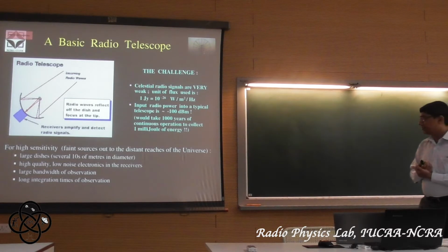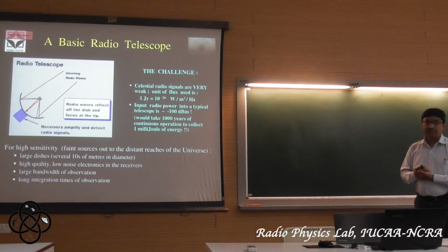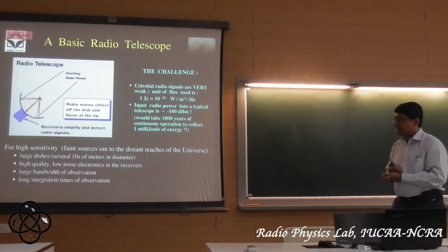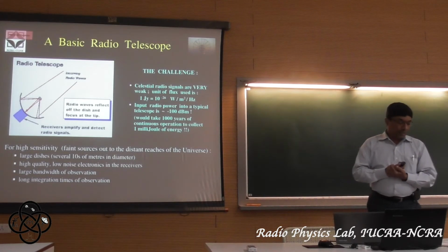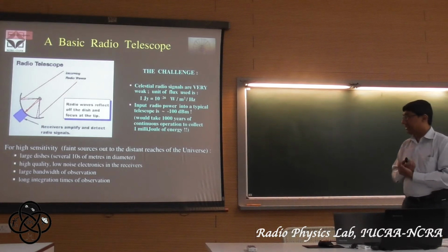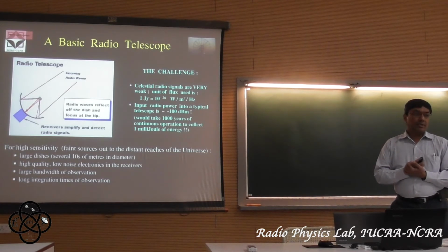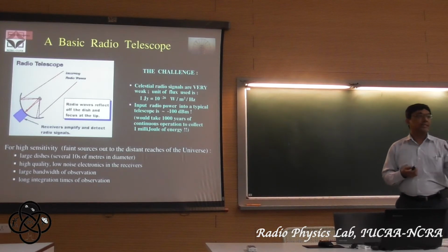Okay, and there are various ways of looking at it. If you understand electrical engineering, that's minus 100 dBm, which is compared to 1 milliwatt of power, that much weaker. Or there are other, more interesting ways of looking at it. So the point there is that you can't quite treat it like your basic satellite dish. And so you say, all right, what does it mean? It means that you need a large enough collecting area to be able to collect enough of that signal that you can detect it easily.